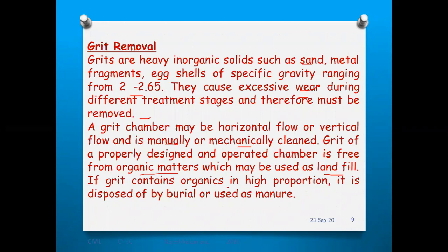If the grit contains a high proportion of organics, it is disposed of by burial or used as manure. Whenever you are having a high quantity of organic waste, it is used for landfill, or if it is uncontrollable, then it is used for agricultural manure purposes, right?